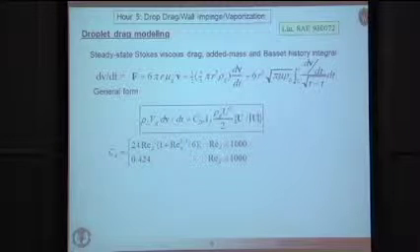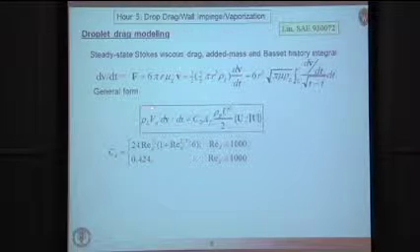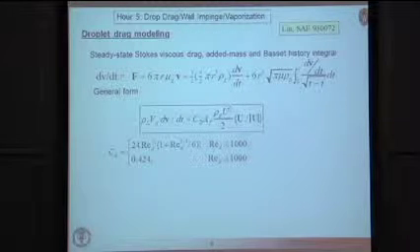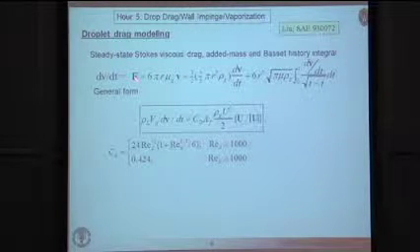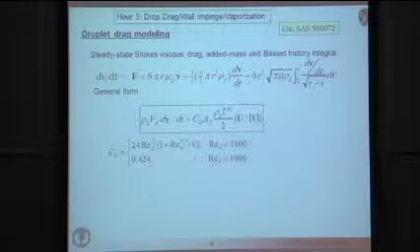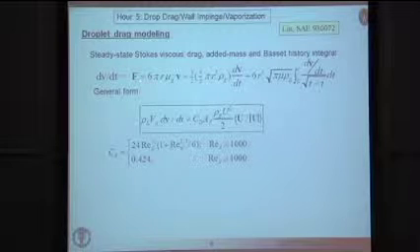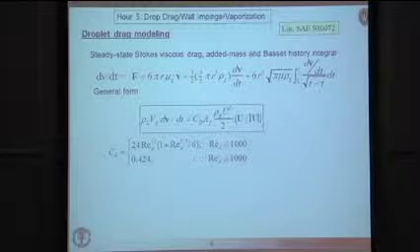So let's talk first about droplet drag. Essentially, here we have the droplet acceleration equals this acceleration function f that we described earlier, that is needed when we go to the source terms in the gas equation. So how do we calculate f? If you look in the literature, a lot of work has been done on drag around objects, and in particular for spherical particles.